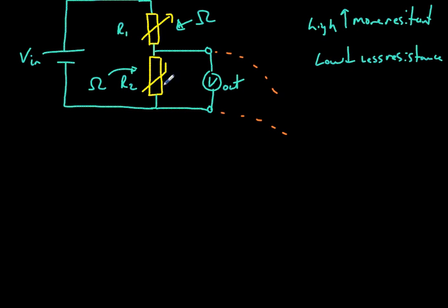These can be used as well. If we were to put an LED across here and have a variable resistor here, you could use it, I guess, as a way of dimming or brightening up the LED. But in general, I do not believe they're used as a transformer. You don't generally want to use this as something that's going to run a lot of current through here. So if it's something small like an LED, probably you're going to be okay, but you wouldn't want to try to run a motor on a voltage dividing circuit. There's other ways to do that. Okay, so we know this, right?